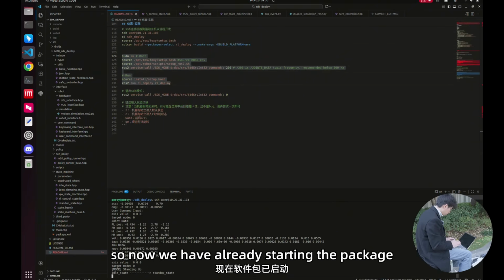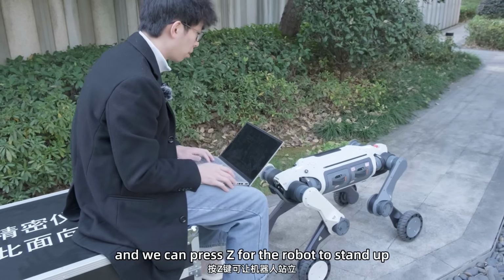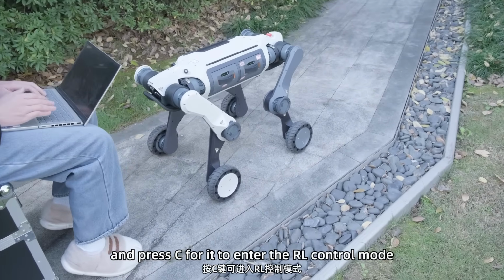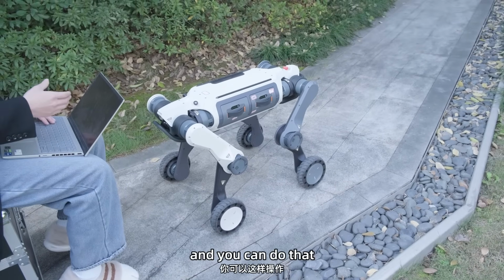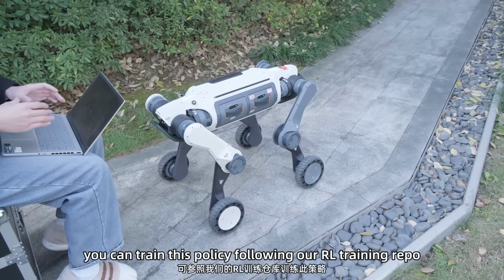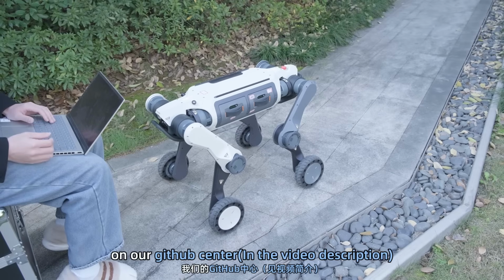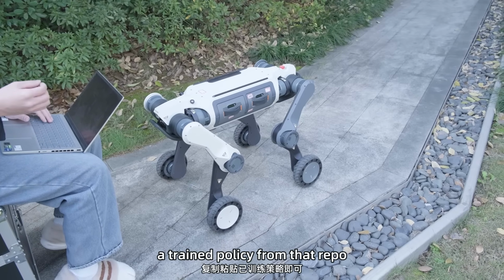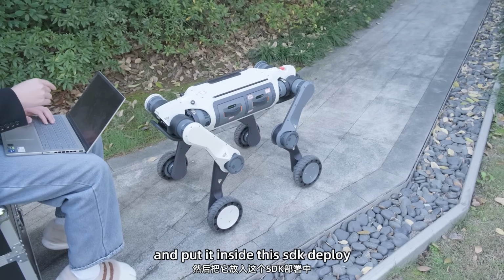So now we have already started the package, and we can press Z for the robot to stand up and press C for it to enter the IO control mode. So this policy is a very simple policy, and you can train this policy following our IO training repo. It's also another repo on our GitHub. We just copy and paste a trained policy from that repo and put it inside this SDK deploy.